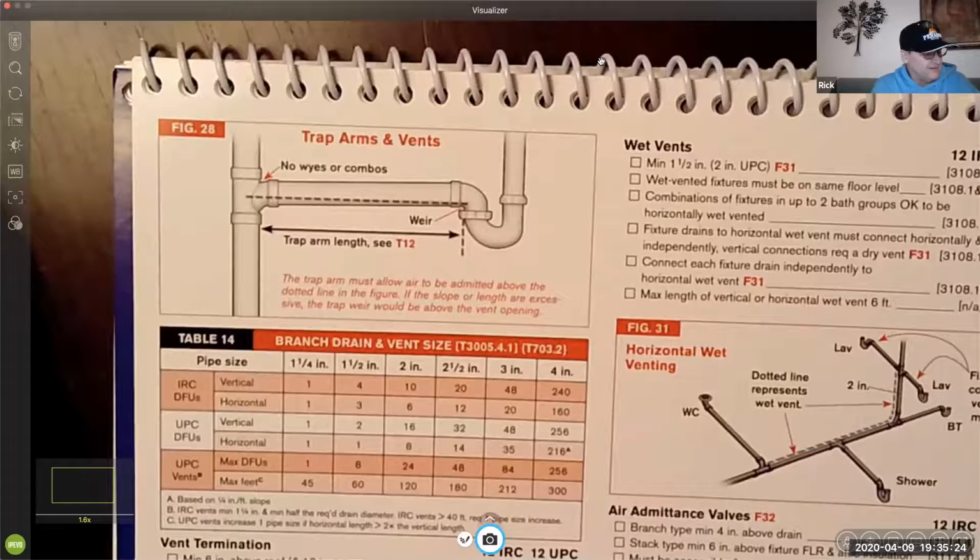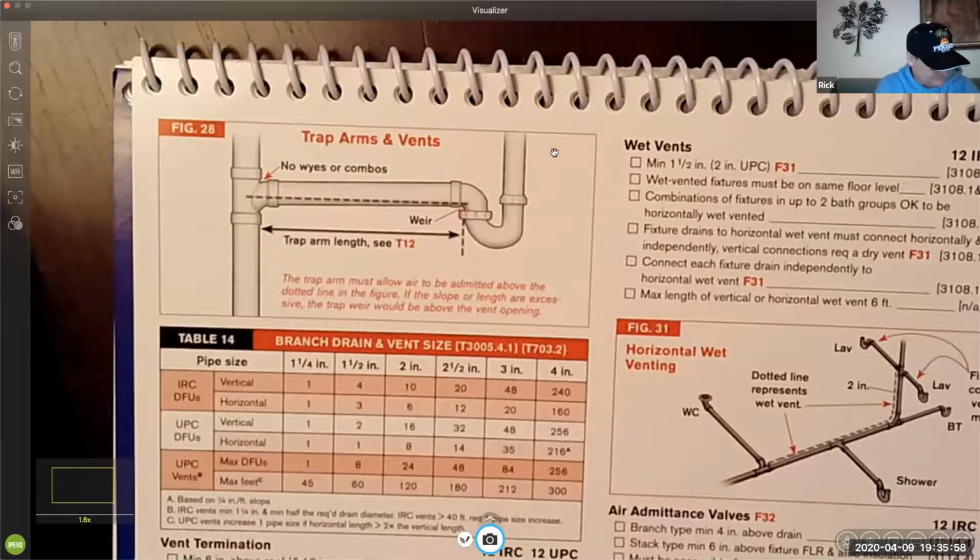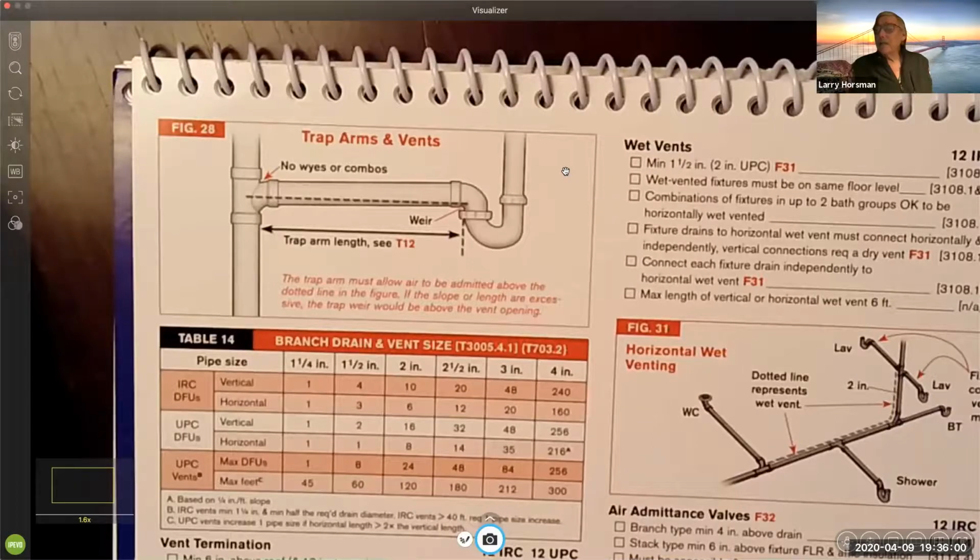Yeah, if you have a floor drain, which is usually an emergency backup in case you have a sink overflow in a commercial establishment or in a public restroom where the sink or the toilet may overflow, then usually you're required to have what's called a trap primer. And so that senses when that trap is gone, and then it will spritz water into the trap to maintain the trap seal. Trap primer. I want one of those. Yeah, well, you may have to put one in some cases.